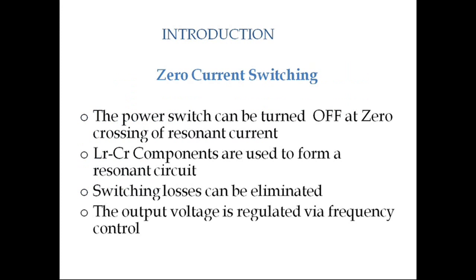Before getting into the details of this project, we need to know about zero current switching. This is the power switch used in the circuit. It can be turned off at zero crossing of resonant current. In this project, the output voltage is regulated by a frequency control.